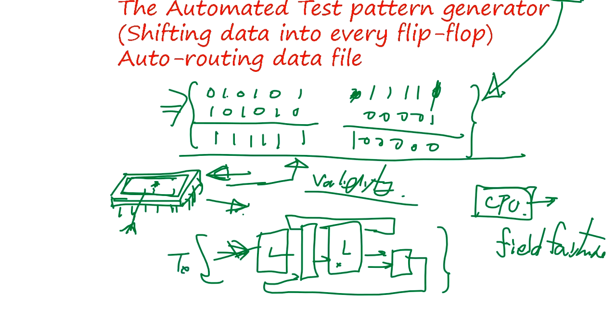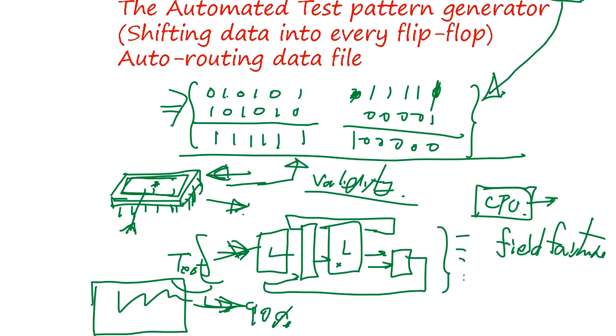If there is one defective transistor here, you may not come across it with a given test pattern. So the question is how much the test pattern can cover any defect on the logic elements. Okay, so that coverage had better be over 90%, right? And it's very hard to reach that, even if you increase the number of random test patterns and check expected output patterns. The reason is the internal register memory elements. It is very difficult to test every case, because one particular internal flip-flop may rarely get 0 or 1. For example, this is an exception flag, and that kind of exception doesn't happen that often, so you may miss it, right?